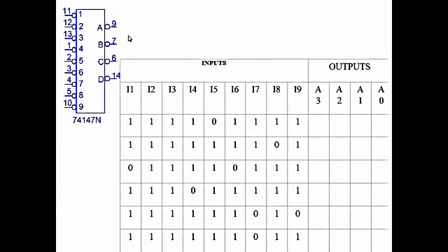Okay. This next one is actually an encoder, and an encoder, remember, converts a decimal number over to a binary number or some other number. In this case, it is a BCD number. This is a 74147. The N is some kind of designation for the chip, but we don't need to worry about the N. It's a 147 chip. Again, it could be 74LS147, could be 74147 by itself. There's a CMOS version of this. That's the number we're going to look at for this chip.